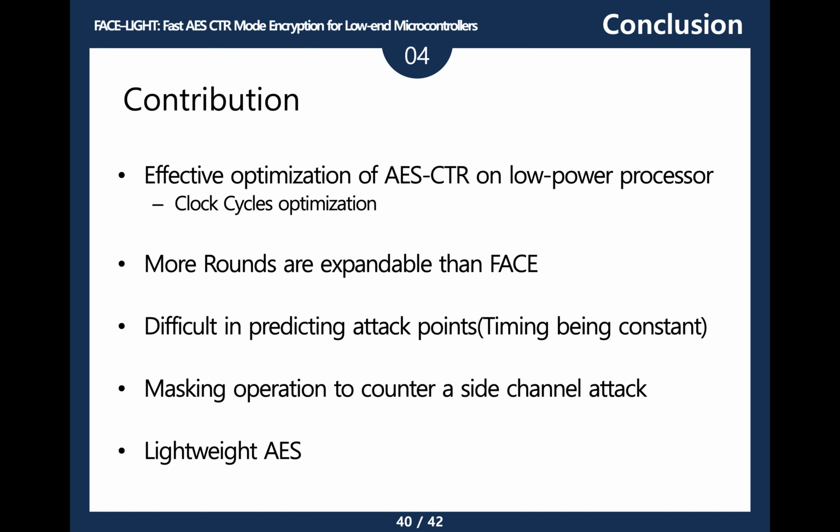Also, our work is more expandable than the phase, and it is more difficult to predict attack points since it runs on a constant timing by not having to update a table. Also, we have applied a masking technique to our work in order to counter the side channel attack, which is a must-have standard for modern cryptography.